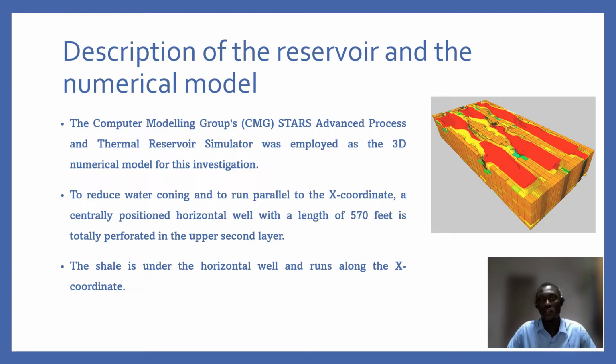And this is demonstrated in the picture below. To reduce water coning, a centrally positioned horizontal well running parallel to the x coordinate, with a length of 570 feet, is completed in the upper second layer, and the shale is considered to run along the x coordinate.